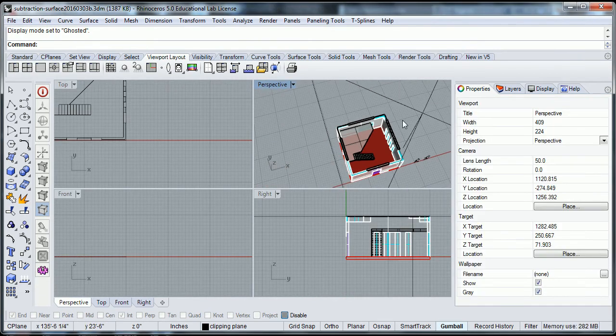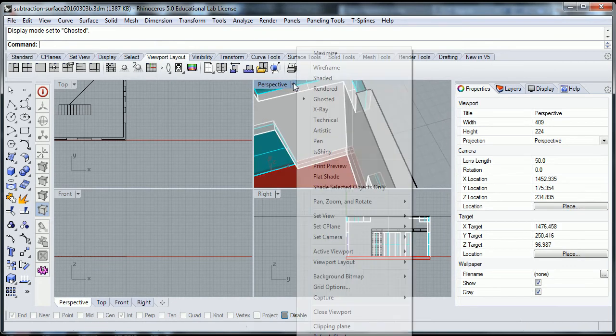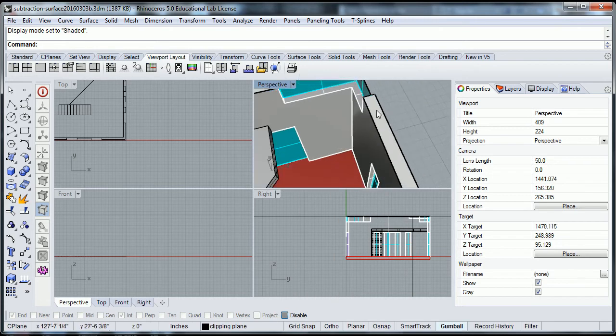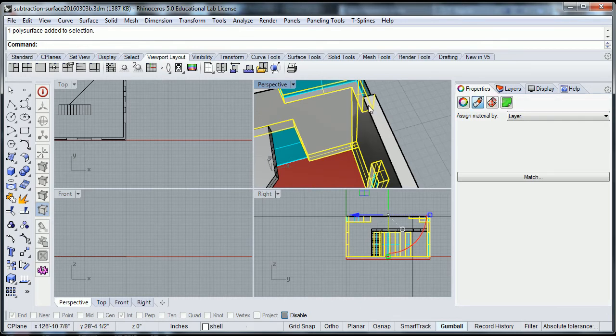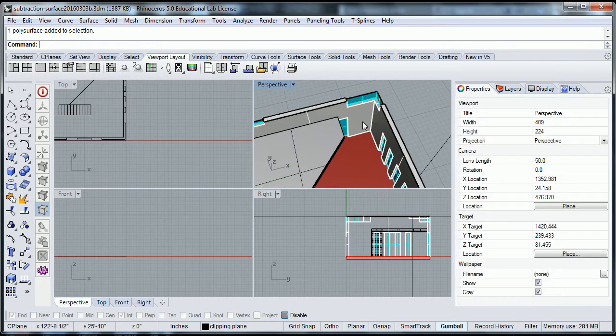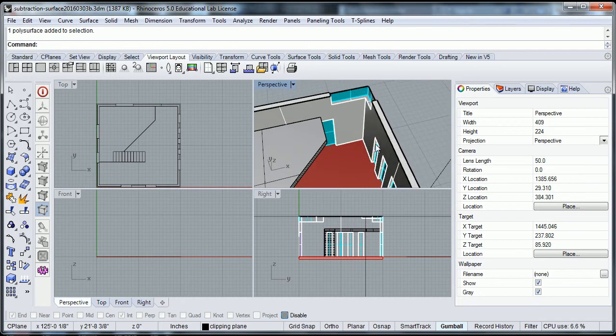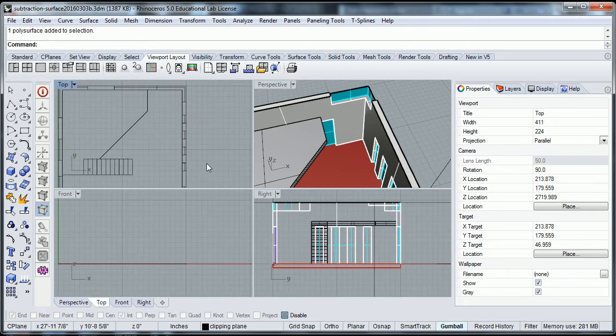I'm not sure why it's showing up that way, but for some reason in shaded view the Rhino model is showing this as solid. Usually it shows as just a wire frame like thing, so you could see inside. The problem is that when you make 2D, it is telescoping what's under here onto this surface. So you're just looking right down this wall, and that's why it makes these windows down here.